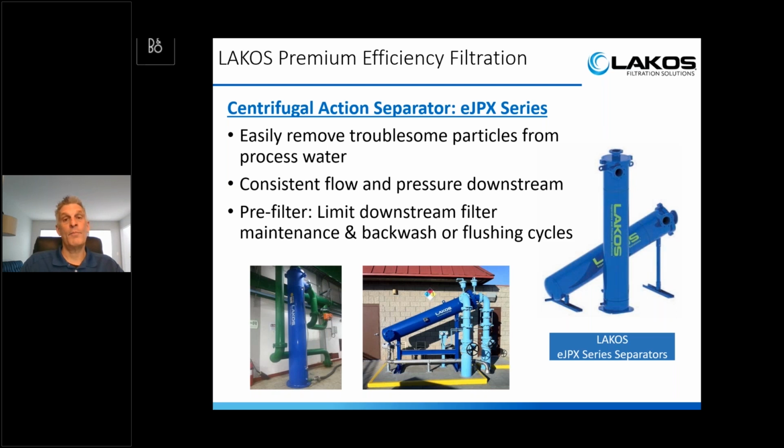You have consistent flow and pressure downstream, which is very critical, especially for spray nozzles or heat exchangers. And in a lot of cases, separators are used as a pre-filter to limit downstream filter maintenance, and of course, extending out backwashing cycles or flushing cycles when it comes to screens and media tanks.